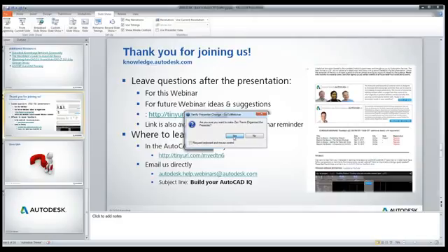So what I've done is I've changed the startup variable from 3 to 1, and to do that I just typed in startup at the command line, changed it to 1. Next time I went up to the top and said File New up here in the corner, it brings up this Create New Drawing wizard, and you can do a few things here. You can open a drawing from a folder with this first button. You can start from scratch.